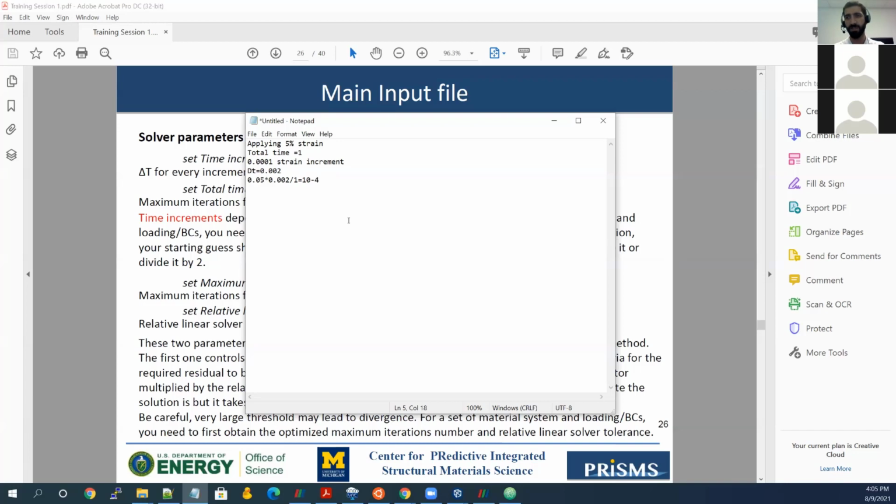Now, if you do the simulation, your initial simulation, and it diverges, then you need to divide this by a factor of 2. So the next delta t will be... Now if it actually converges with delta t equal to 0.02, you can actually multiply that by 2, which I rarely see the case that it actually gets larger for the material of FCC copper.